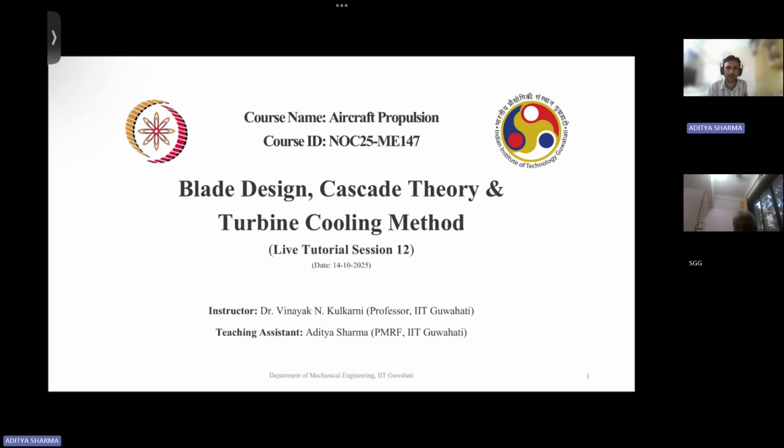I believe I have done this question in this tutorial session. There, we calculated the isentropic T naught 3 dash from the pressure ratio. Then we have the efficiency of the compressor, which is T naught 3 dash minus T naught 1 divided by T naught 3 minus T naught 1.